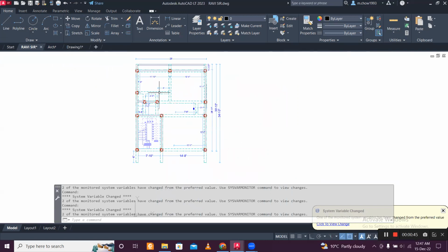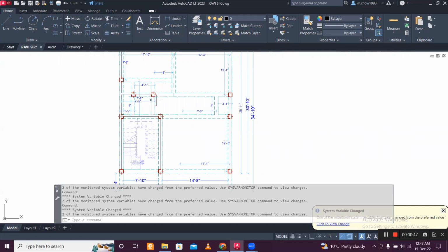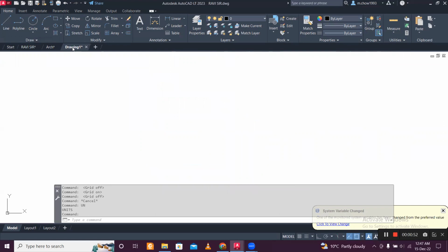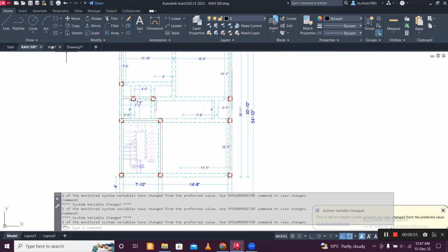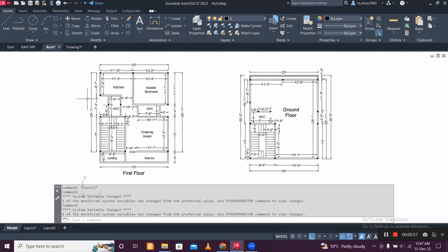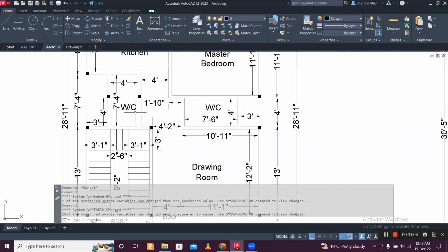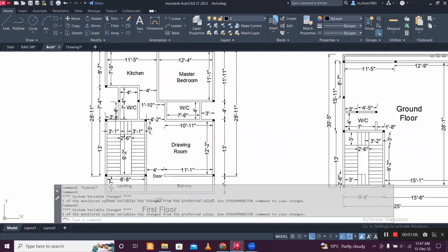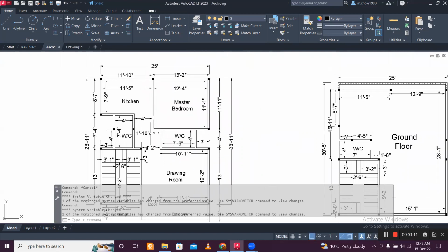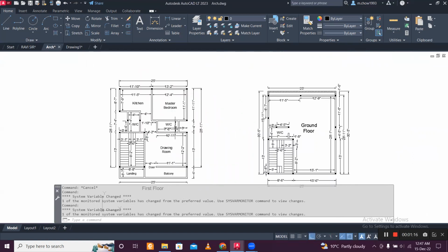It is the kind of same for the ground floor and first floor. The primary beams will be the same. So let's design the primary beams. There are not many secondary beams here, as you can see in the architectural plan also. Most of these are primary beams, and only this beam will be a secondary beam in the first floor, and this beam is a primary beam. There will be one more secondary beam here in the first floor, and here also one small secondary beam. All the beams are column to column, or primary beams.